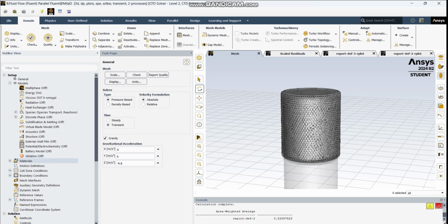We approach this problem using, as you see, computational fluid dynamics. First, I'm going to model both the fluid flow and species transport with the volumetric reaction. And we will simulate two scenarios. Case 1, low mixing speed, 10 radians per second. And the second scenario will be high mixing speed, with 25 radians per second.